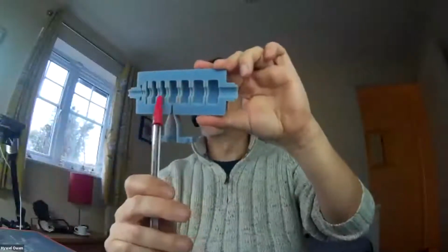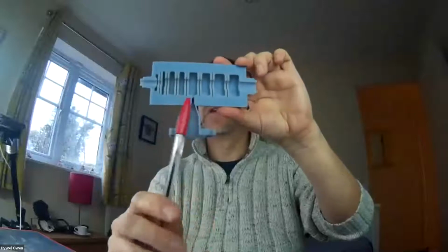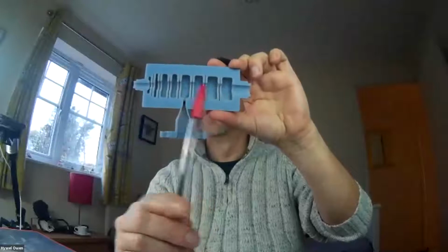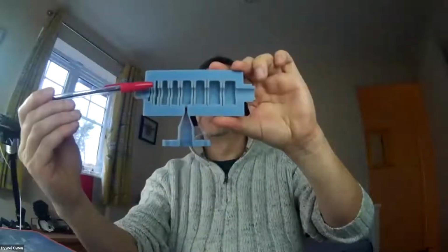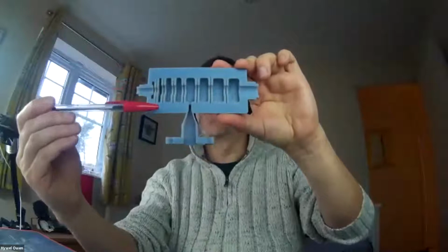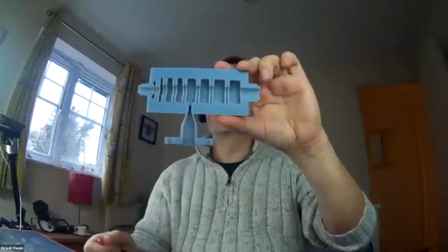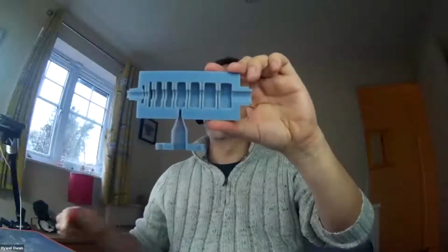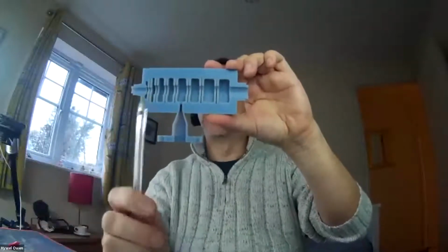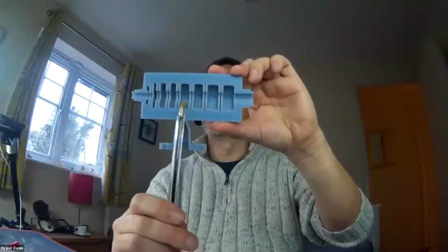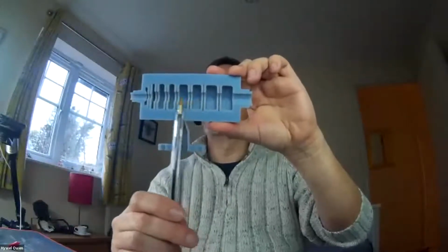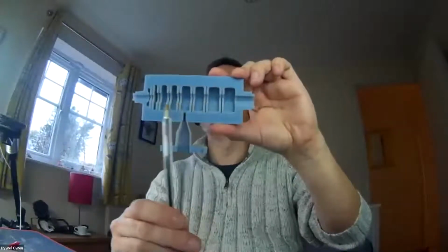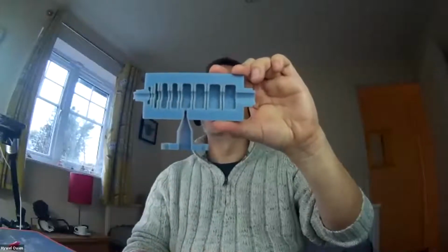little apertures. Okay, and you can see here that there is some kind of hole going in and out at one end of each of those cells. But the commonality is that the diameter of these circular apertures is the same for all of them. So therefore, they all have the same resonant frequency. And because they all have the same resonant frequency, that means that they can pass small amounts of electrical field from one to the other through these apertures. So they will all be coupled together. These are coupled oscillators, and they all resonate together.